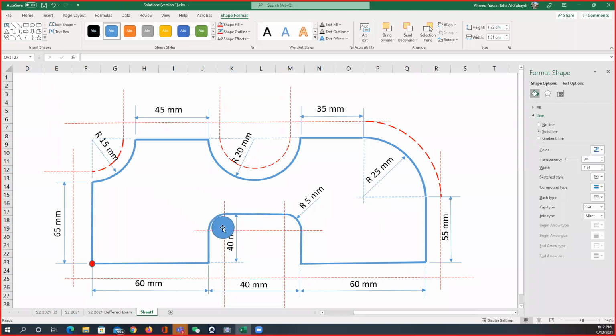the code to be written as a G02 or G03 at that point, because the radius of the cutting tool will make the cut as the cutting tool is going to pass here. So this will be the cutting tool. When it's going to come to here, it's going to generate that arc. That's a very important thing you need to remember.